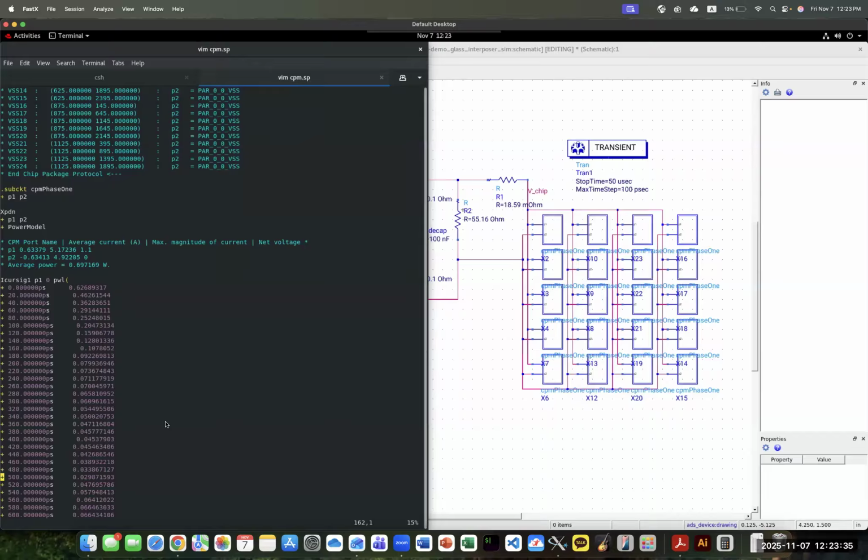There may be different answers for the power side and for the ground side, which is common across everybody. I would think when all of them are running at the highest frequency, that would give you the largest noise and higher drop. But are you looking at running these at different frequencies where you would start getting harmonics and stuff? Or is it just the parasitics where you're going to get time skews anyhow?